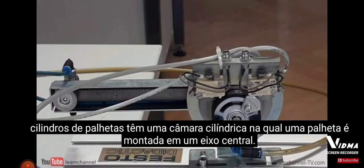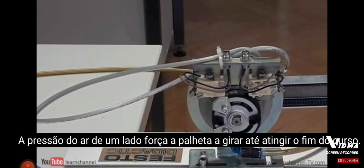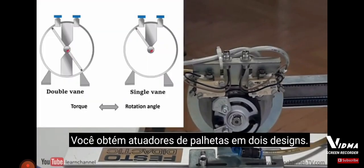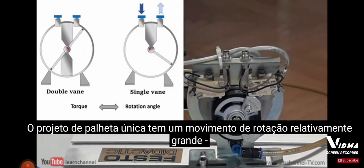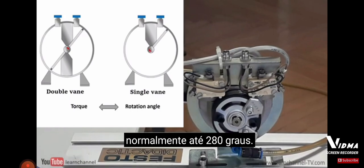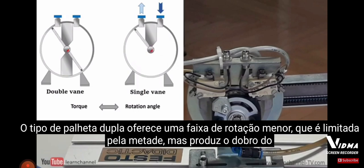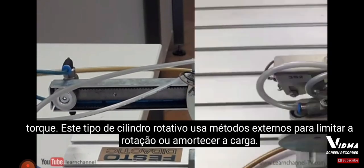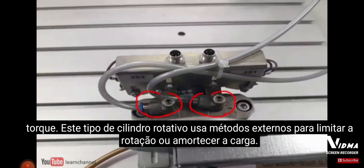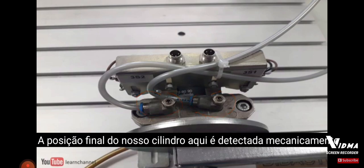Vane cylinders have a cylindrical chamber in which a vane is mounted to a central shaft. Air pressure on one side forces the vane to rotate until the end of the stroke is reached. You get vane actuators in two designs. The single vane design has a relatively large rotary motion, up to 280 degrees typically. The double vane type offers a lesser rotational range, which is limited by half, but produces twice the torque. This type of rotary cylinder uses external methods to limit the rotation or to cushion the load. The end position of our cylinder here is detected mechanically.